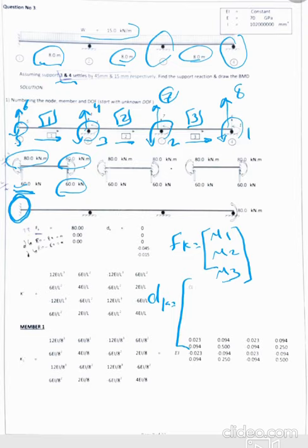So take the vertical direction, then D4. Here the D4 on node 3 is 0. We don't have any settlement or any applied load or anything. D5 is actually the M5, and M5 is 0. We don't have a moment on node 1. Then D6, because it's the force, not moment, so I mention it as D. D6 is 0.